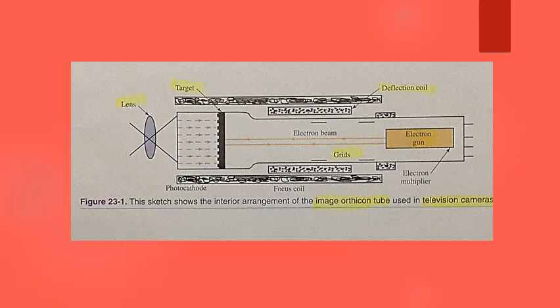As a television camera views a studio scene, it sees the scene as a combination of these picture elements. The scene is focused on a photoresistive mosaic in the camera that consists of many photoelectric cells. Each cell responds to the scene by producing a voltage that is in balance with the strength of the light. These voltages are amplified and then used for modulation of the AM carrier wave. This wave is transmitted to the home receiver.